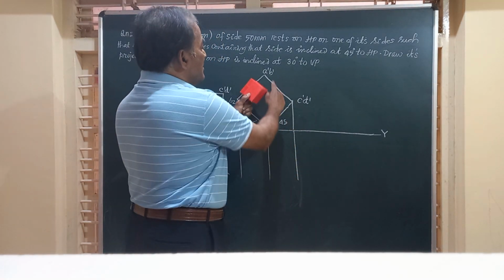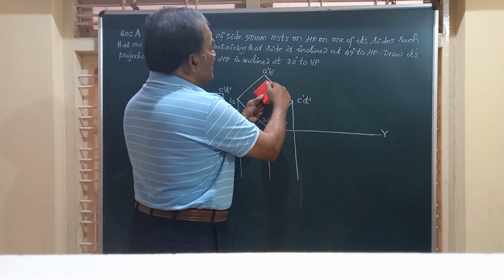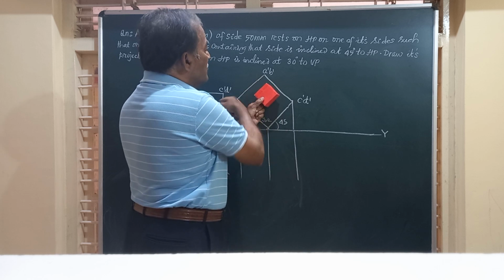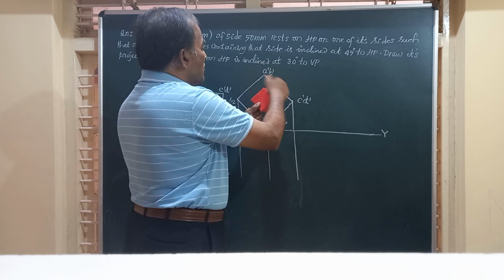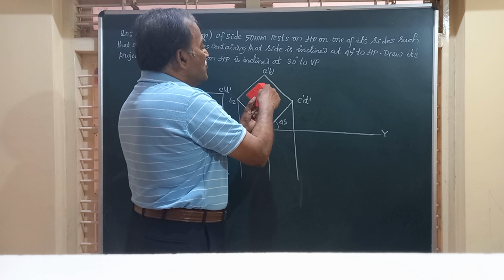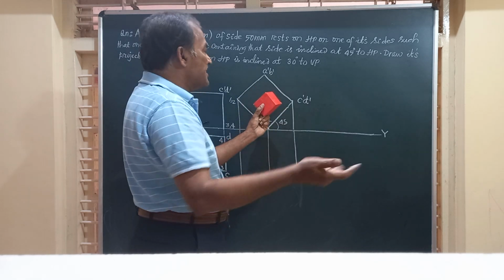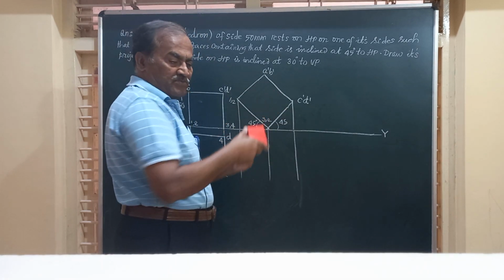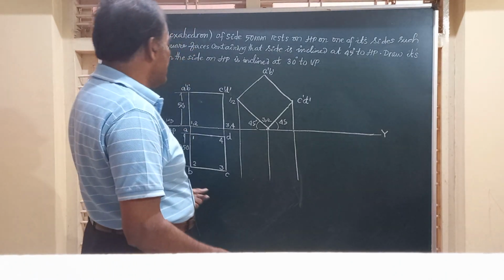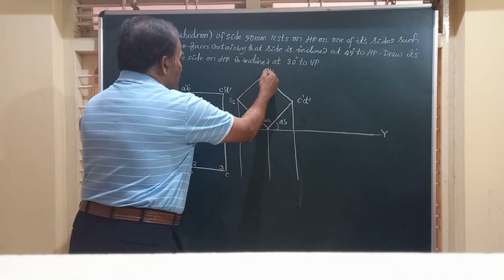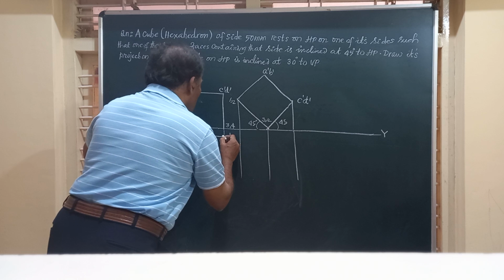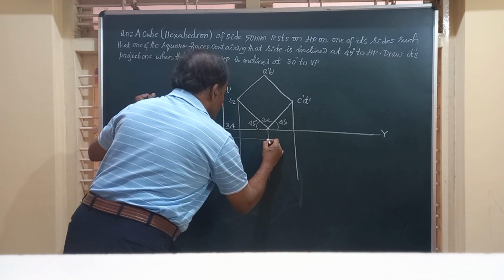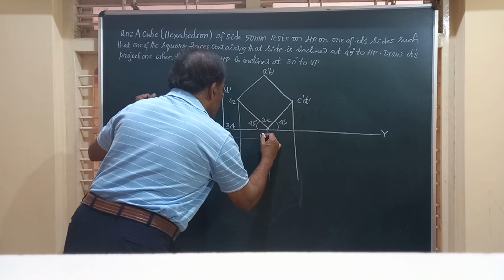This surface is ABCD. This is seen and AB12 is also seen. So in the top view, you are going to have two square faces seen as rectangles. So it becomes a rectangular surface. Friends, let us take points one by one. Vertical from A, horizontal from A. This point will be our A.